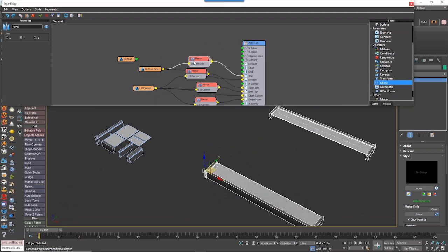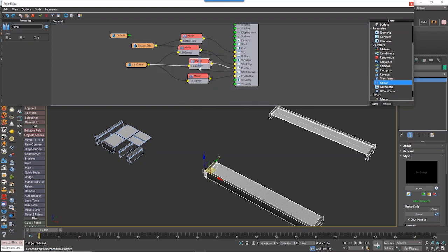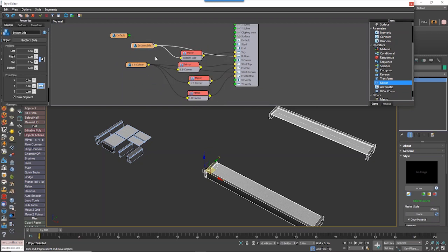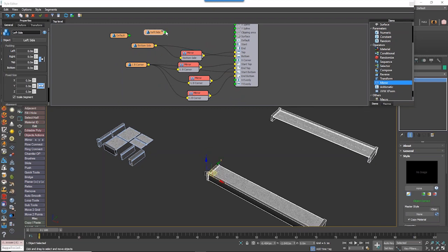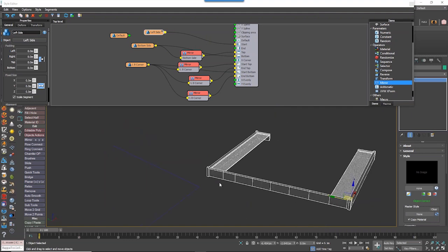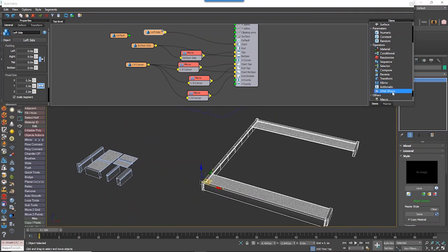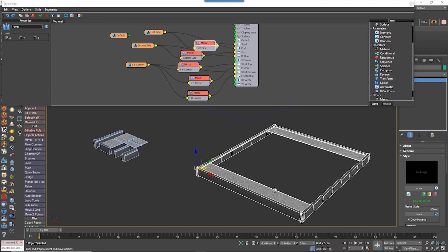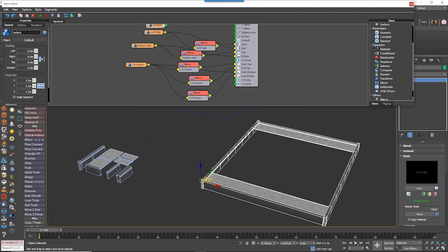Good so far. So now we need the left and the right hand side of this array. So let's just move all this down a little bit so we can see what's going on. Take this and clone it. Take the left hand side and wire it unsurprisingly to the start or the left input. So that's in there now. If I want it on the right hand side, well, I haven't got one for the right hand side, but I can mirror it. So I only need to model it once to the end. So I've got it in that side now. And then I could connect my glass back up.